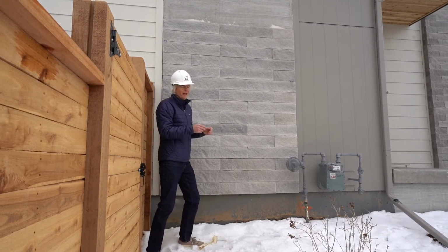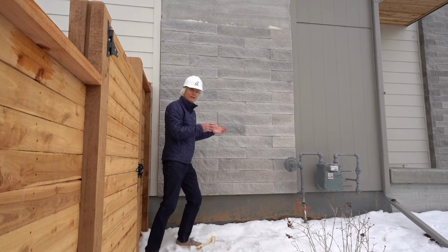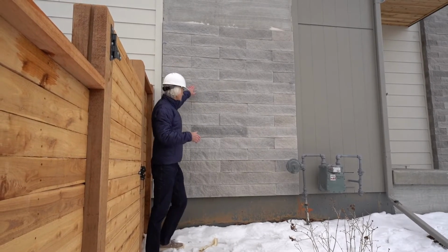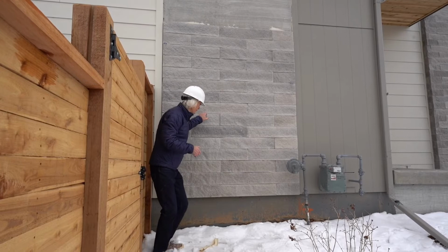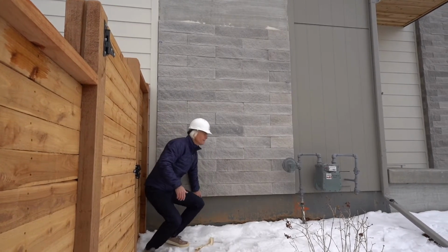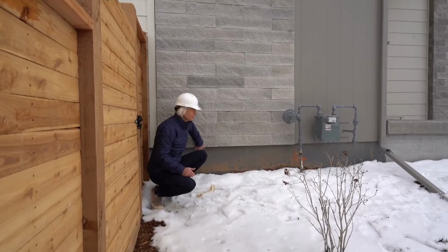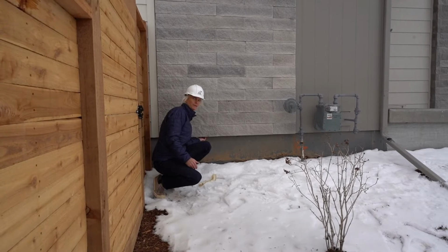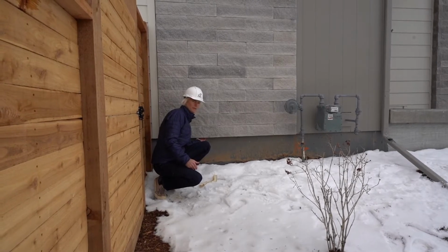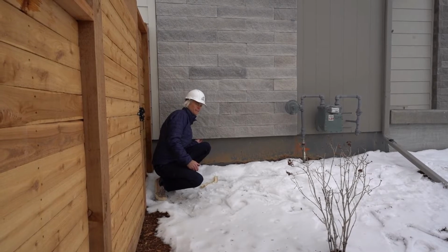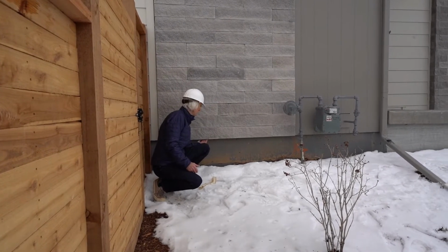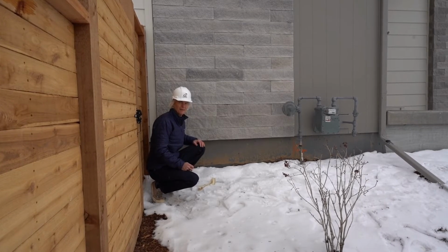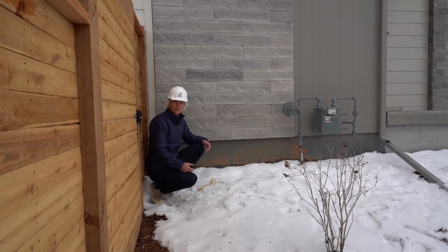So this is a technical challenge. We think about flashing it, integrating it into the building, and then how are we draining it? When we look at that scratch coat, it's an open joint stone that's on here as well. We can see even at the bottom of the wall, there was basically nothing down here. I'm reaching up and I can feel the OSB right here on this bottom edge. And then there's a small piece of metal that's just a J-stop. It's not even a weep screed. I don't feel any holes in it. And then the stone is right here on that scratch coat. So pretty basic install when we look at trying to deal with inclement weather.